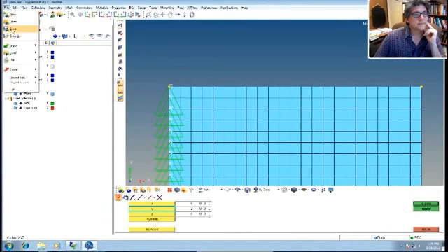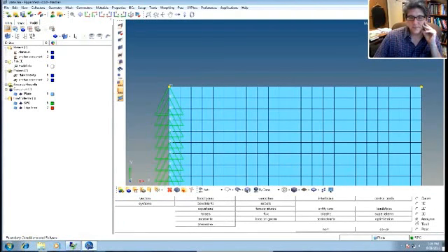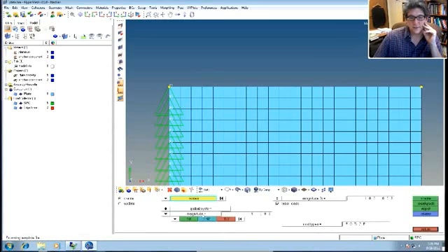Let me save it. Well, it's not. Oh, there it goes. Now it goes back. Okay, fine. So to create a force, it's under Analysis, just like constraints. And then we're going to pick Forces. Now, when you do a force, you pick the node. You also have to pick the magnitude. That's the number value, so it's going to be like 3900. And then the direction. Okay?